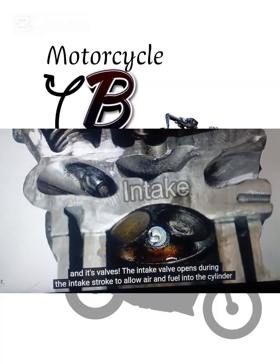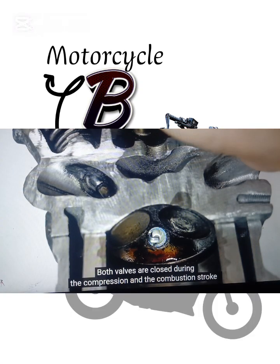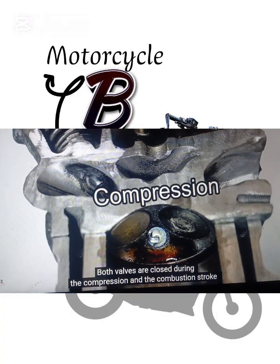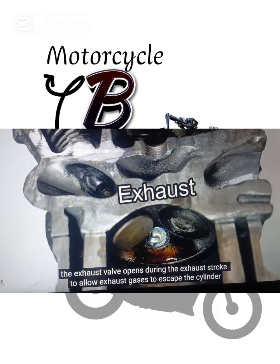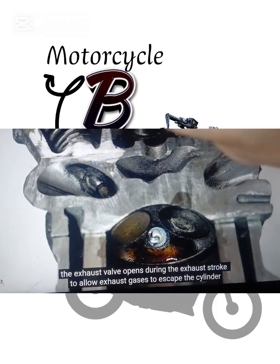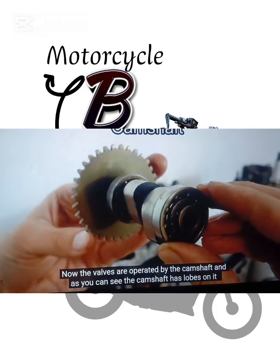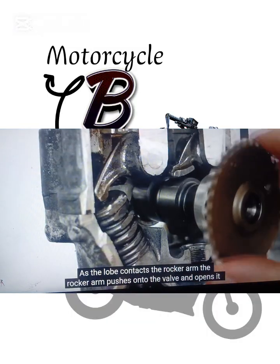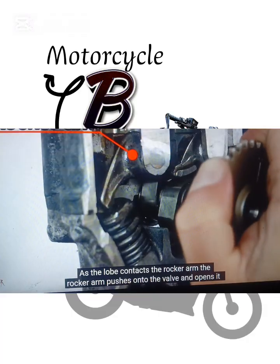The intake valve opens during the intake stroke to allow air and fuel into the cylinder. Both valves are closed during the compression and the combustion stroke to prevent air and fuel as well as combustion energy from escaping the cylinder. And finally, the exhaust valve opens during the exhaust stroke to allow exhaust gases to escape the cylinder. Now the valves are operated by the camshaft, and as you can see, the camshaft has lobes on it. As the lobe contacts the rocker arm, it pushes onto the valve and opens it.